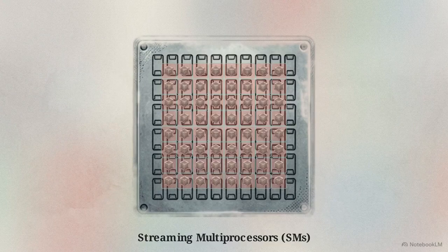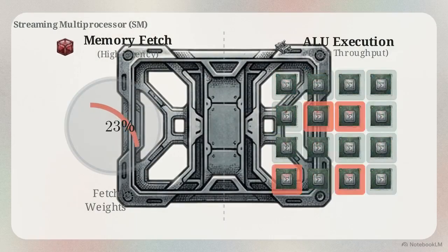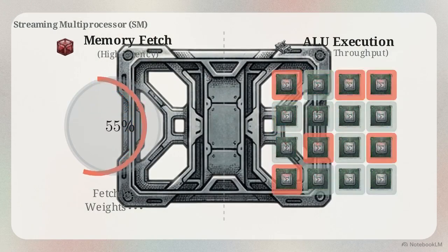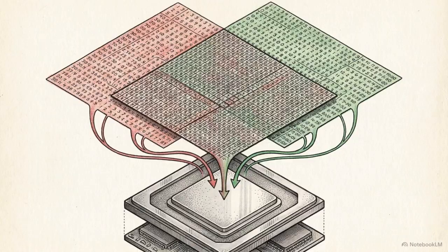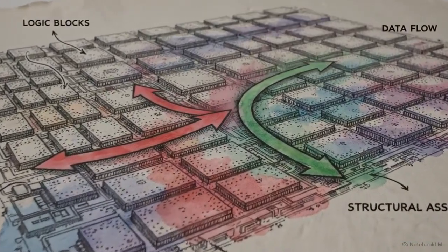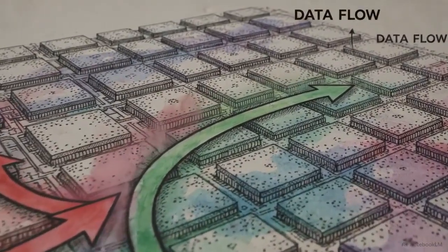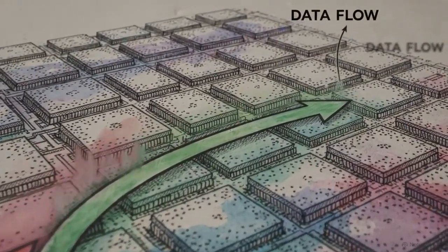During the initial kernel launch, distributed grids of thread blocks are dispatched to individual streaming multiprocessors across the die. Inside the SM, warp schedulers interleave instructions at high speed, hiding memory latency by constantly keeping the arithmetic units busy while the local caches fetch the next set of weights. Specialized tensor cores then execute the high-throughput matrix multiplications, rapidly processing the neural network layers using reduced FP16 or FP8 formats. The modern hardware stack functions as a specialized hierarchical matrix engine. Here, software performance depends entirely on mastering parallel concurrency and silicon-level memory proximity.